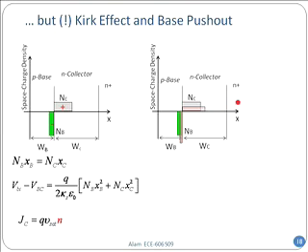So the depletion region, which originally didn't have any charge, right? It was completely space charge region, fixed charges. Now there will be electrons flowing, and with a lot of electrons, the number could be almost comparable to the background doping. In that case, I cannot neglect the small n and small p, the electron number, in the Poisson equation. And in that case, my new equation should be NB plus N.